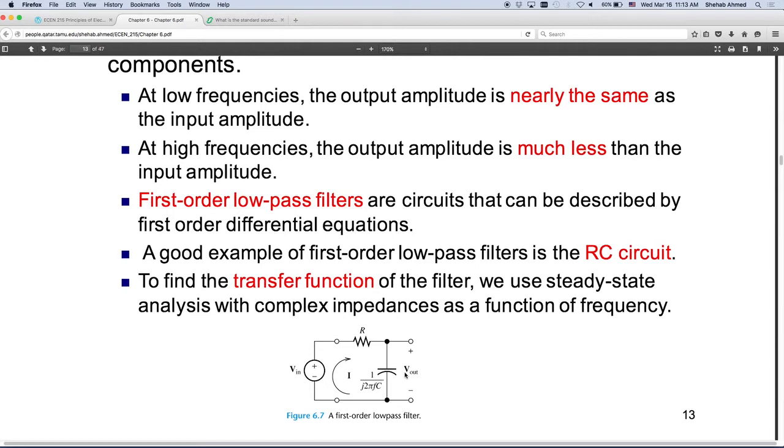When you study control, you'll see that the order of an electrical system depends on these energy storage elements, because each of them affects the time domain change of the system. Resistors don't have any dependence on time: you put in voltage, you get current that looks exactly the same. Inductors and capacitors have a time domain dependence of voltage and current through and across.